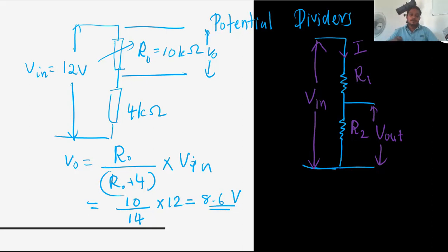Okay. So the second part: explain without further calculation what happens to the output signal if the resistance R is decreased. If R is decreased, what is happening? You can see here, the output resistance is decreasing and this is also decreasing, but this decrease is not that important because basically we have a constant value now.